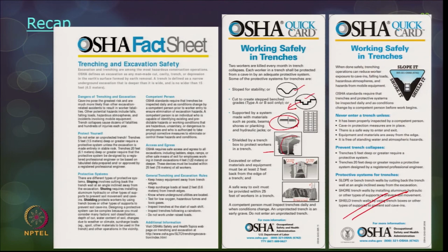Okay. And always maintain a 2 feet clear distance on the edges, okay, clear width, and do not deposit any sort of excavated material or your equipment there, nothing should be seen there, and a safe way of exit must be provided within 25 feet of workers in a trench. Okay. So, these are all a recap of what I have covered so far.